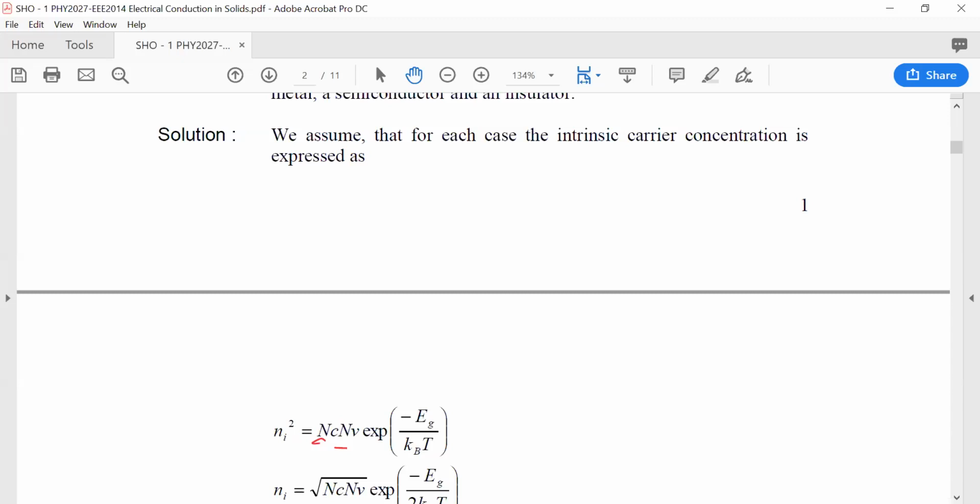As we've been through, the electron concentration is also highly dependent on the band gap of the material. And this term in the equation indicates e to the minus Eg over 2 kBT, where kBT over q is the thermal voltage and constant for a given temperature. At room temperature, we're going to assume the thermal voltage is 0.026 volts. And this is also on your data sheet in the upper section if you want to have a look at that. There's no need to multiply the Boltzmann constant kB by the temperature each time.